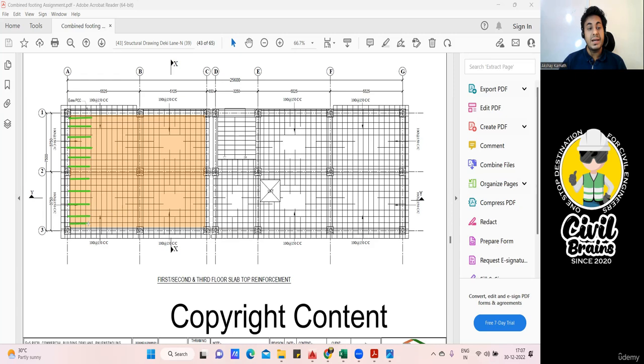Tell me how the bending moment diagram of a slab will look. It's similar to the beam, if you remember. If I ask you to draw the bending moment diagram, here we'll be having a negative bending moment. Why is it negative? Wherever there is a slab and beam junction, you'll be having a negative bending moment. Then it will be a sagging bending moment. Again, at a beam and slab junction, negative bending moment. Again positive, again negative. Got it? Wherever this kind of situation arises, we are going to provide top reinforcement.